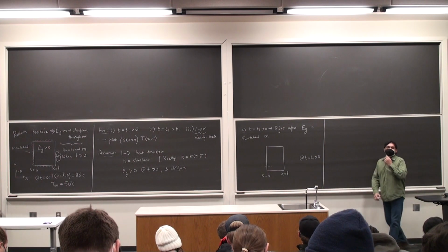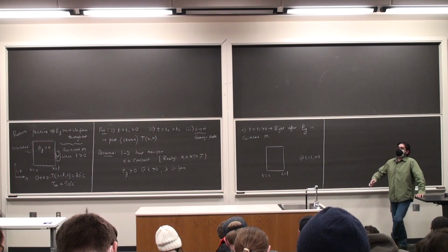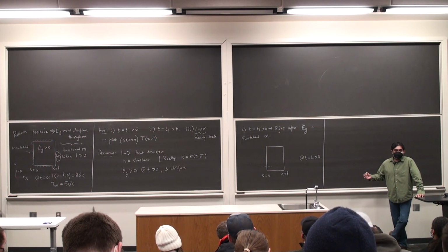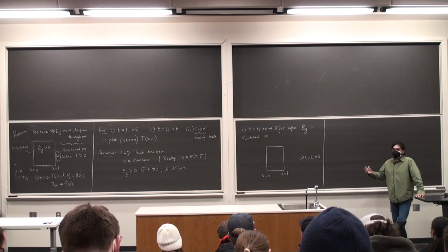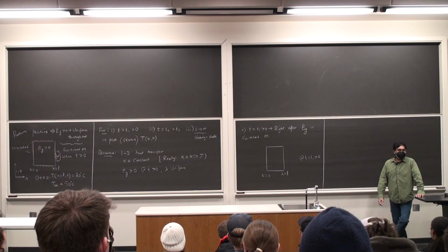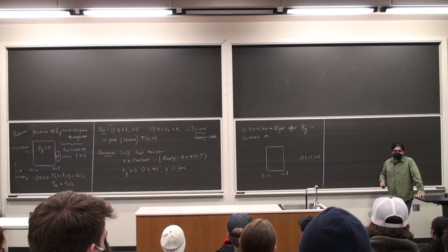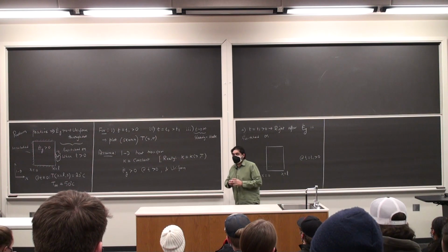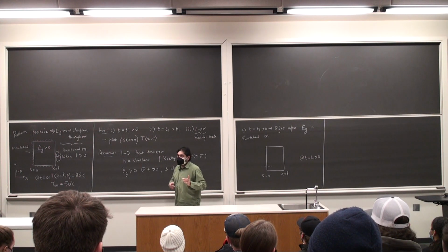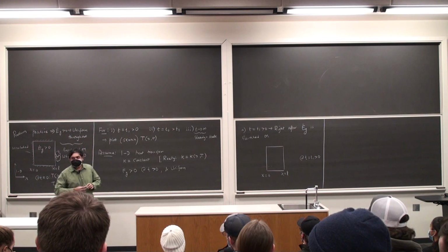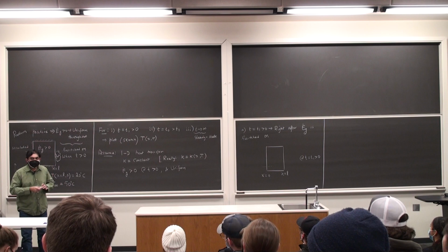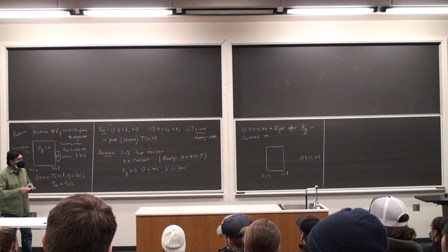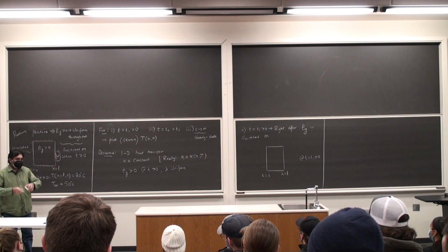Now what do you think is happening at the right side? Is it a 0 slope, a positive slope, or a negative slope? It's not 0 for sure, yes, that is true. So your choices are positive or negative. One of you had your hand up. Yeah. I was going to say positive. Positive, what's your reason for that? Because it's generating heat, even though it's not a lot, it's still generating a little bit of heat. Hang on to that thought, yes. Heat generation is with respect to the derivative of the slope of temperature. So if heat generation is positive, our slope should be negative based on that equation. That's very similar to what you suggested, yes.